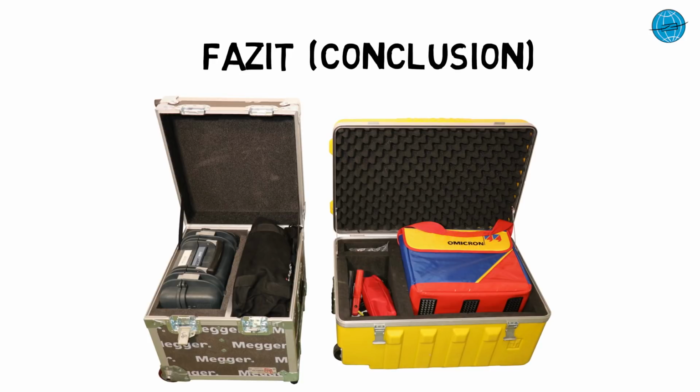The MVCT from MEGGER, on the other hand, is broader in scope, and in addition to the classic current transformer tests, single-phase protection tests can also be carried out. The possibility of integrated isolation testing is a very useful feature in current and voltage transformer testing, although we have not explicitly tested it to our extent. The graphic design of the MVCT is world-class. Due to the large color display, the animation of the demagnetization process is really made for the movies.